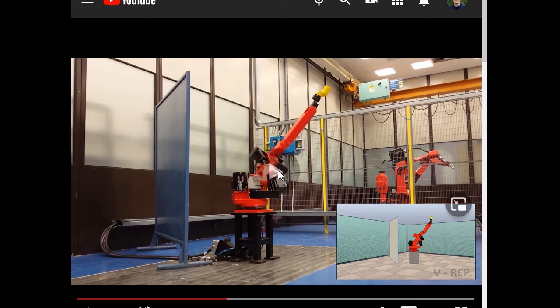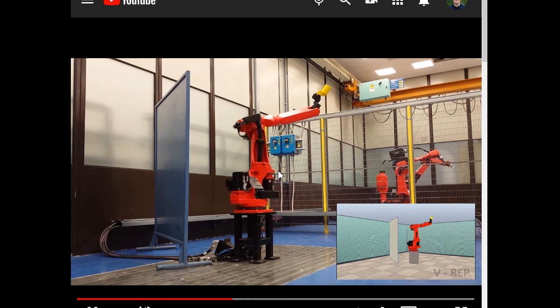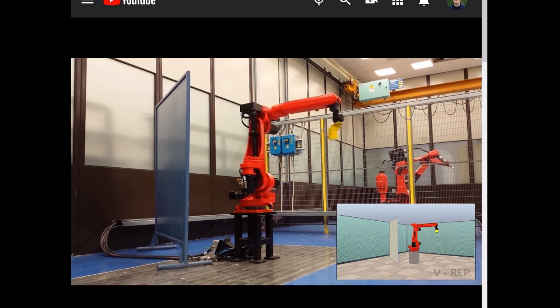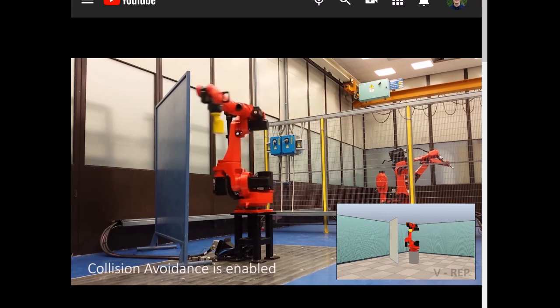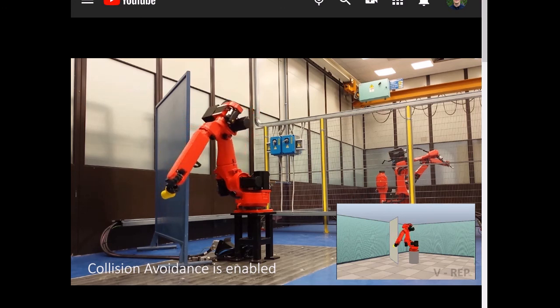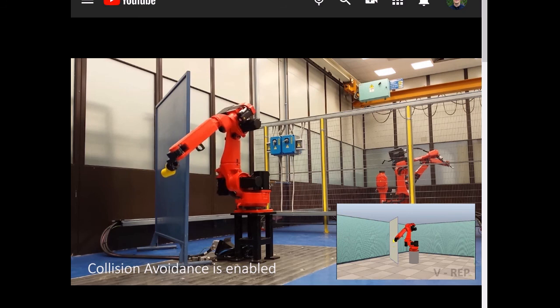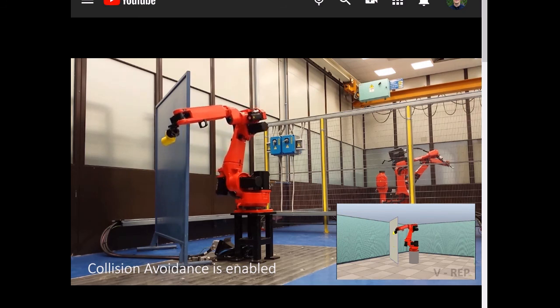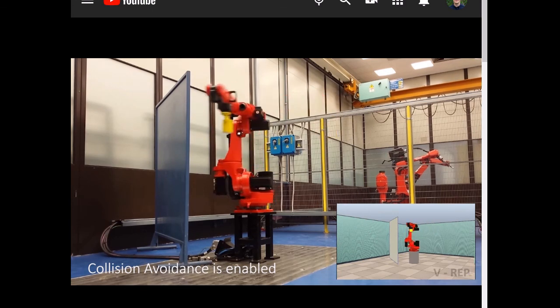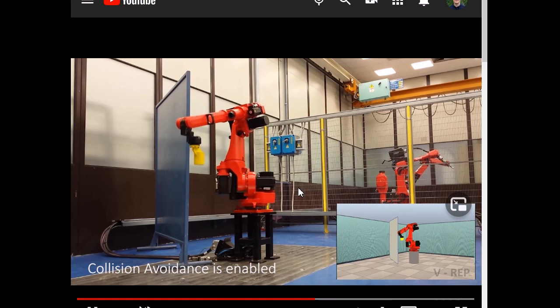Well, as said before, this is useful because, first of all, you can manipulate objects behind walls, and the other aspect is that if you have tight space, as you may commonly find within the automotive industry, where space is quite expensive, you are able to actually perform more tasks in a smaller space, because now you will be able to have industrial manipulators avoid one another better than if you were to have solely 6 degrees of freedom industrial manipulators.